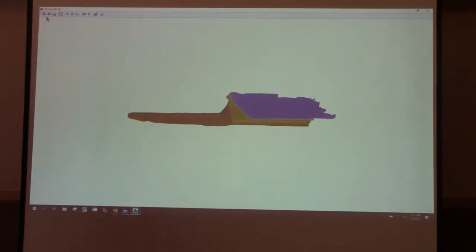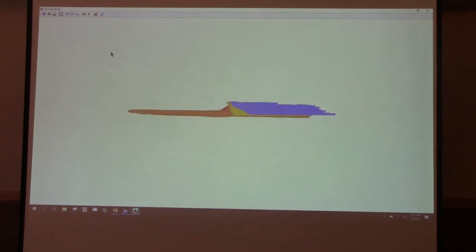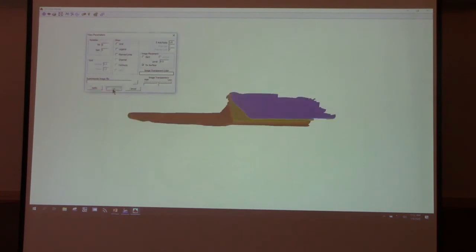This is all geo-referenced data. If you make it a flat projection, you can export to GeoTIFF. But is it a GeoTIFF that's going to display what you see there as a reference? It's going to be geo-referenced with values attached so that, let's say, ArcView could run analysis on it and color it. It's going to be a real-world scale. So if you're in feet, every unit is 1 foot.